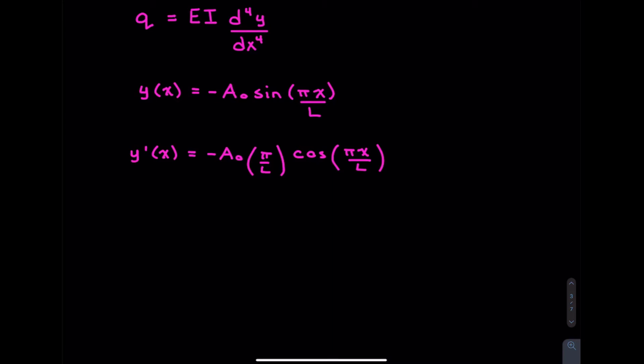If we go to the second derivative, it follows the very same thing, where we take out that baby, so it becomes pi squared divided by L squared, and the cosine changes to sine. The one thing we have to keep in mind, though, is that when we take the derivative of cosine, we actually have a negative that comes out in front. So in the case of y double prime here, that'll actually be positive. However, you guys are already experts, so I'm going to skip ahead here.